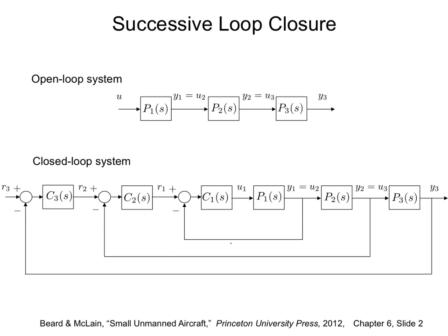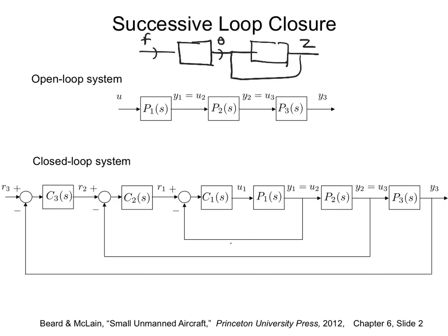think it was two transfer functions, right? And one was F to theta, and theta to z. You remember that? So your position of the cart could be controlled using theta, and theta can be controlled using the force that you apply on the cart, right? So the way you controlled was, you put a PD control here, assuming that whatever theta you are saying is available, that means the inner loop is much faster.